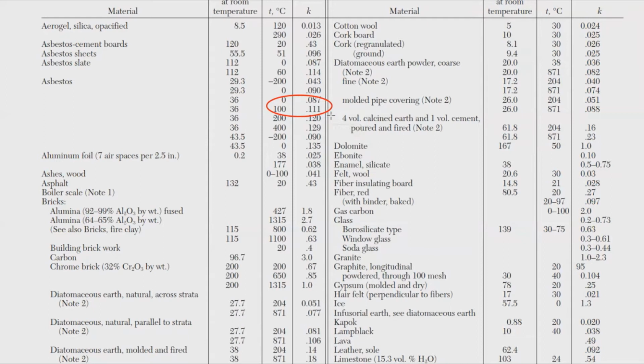Of course, it's greater than 0, but I'm not saying that it's less than 100. I'm not sure of that, but we can simply take these values because it is a more practical way of finding a value which is less than 100, I think. But what if in your solution you chose this one? I still think that it will be okay as long as the thermal conductivity of the asbestos you have obtained is somewhere around here, from 0.087 to 0.120. I mean greater than 0.087.